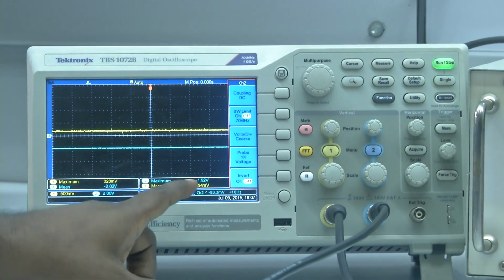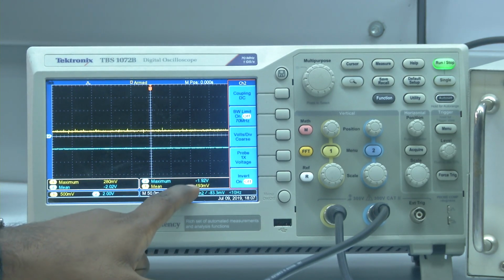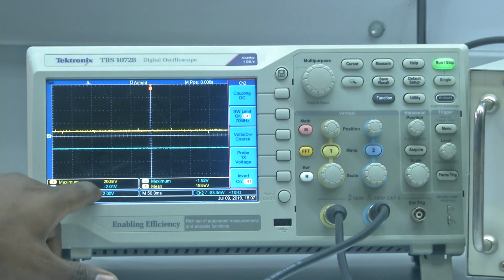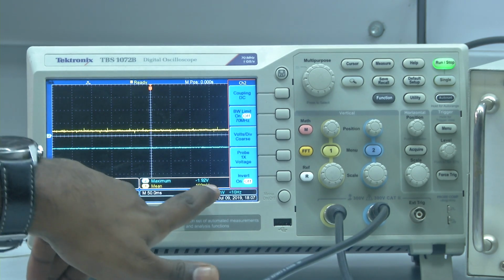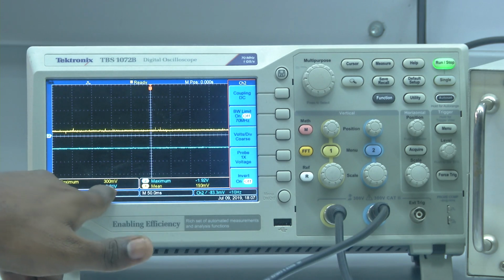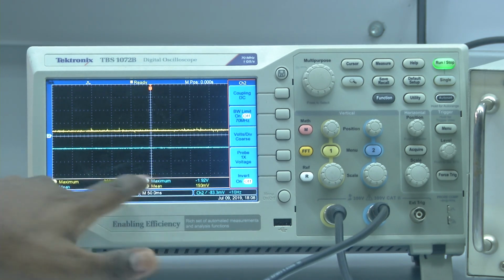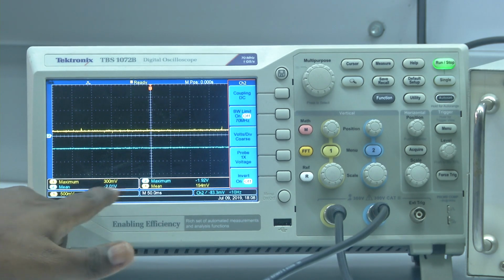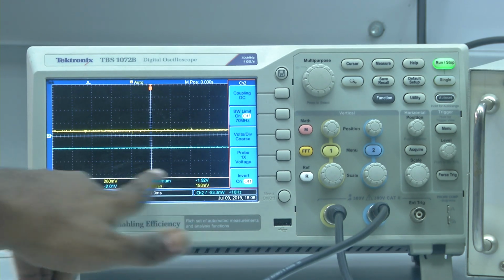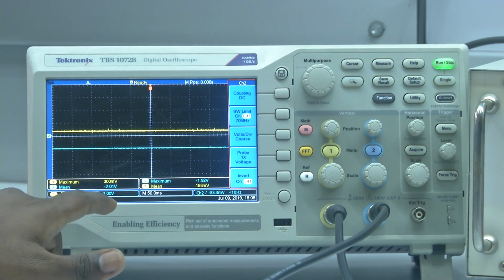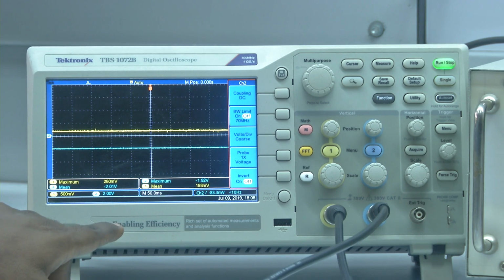So, here if you observe, the mean of input is 193 millivolt, and we are getting close to a mean of minus 2.1. If you observe carefully, the input is positive, but the output we are getting is negative, which indicates that because of the inverting amplifier configuration, we will always have a difference in the phase. Magnitude will be 10 times the input, but the phase will always be different.